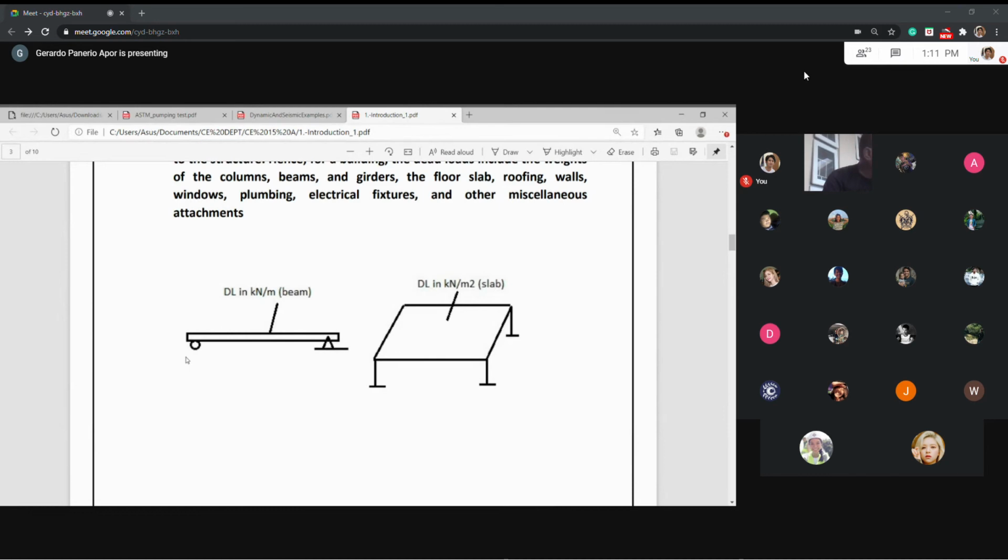This beam is just a line, with a hinge or pin on the left support and on the right support. You can see that this is not very realistic. But this kind of structure appears in most structural theory, even in statics of rigid bodies. There is no actual structure like this, except maybe the beam used by gymnasts, a single plank.